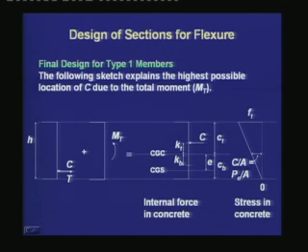In that situation, the stress block that we get in concrete is triangular with zero stress at the bottom. Thus, we see that for transfer and for service, we have satisfied the allowable tensile stress in the concrete, which is 0 for a type 1 member.